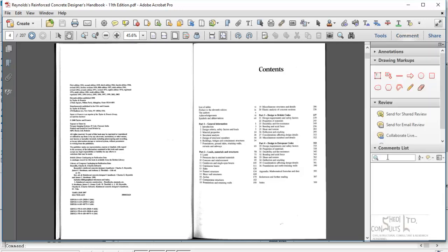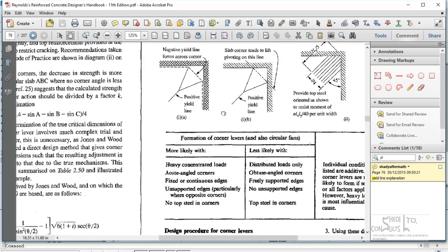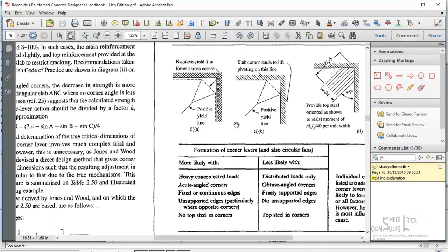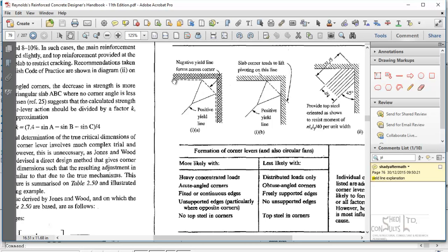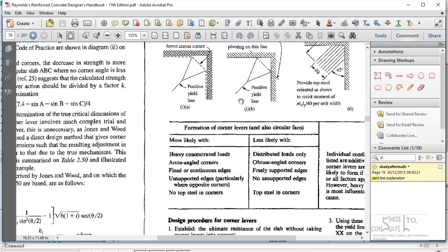Okay. If you look at this carefully, you would see that these are yield line formations. So what are yield lines? Yield lines are the lines in which crack formation on a slab panel would first form, where the slab material would reach its yield point. It is the location where you have the maximum moment, which will cause crack failure on the structure. These are the yield lines we are referring to.